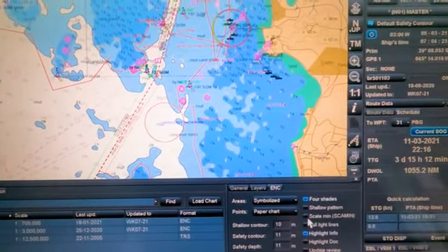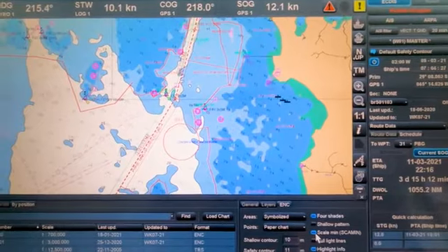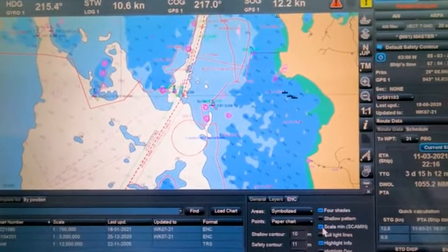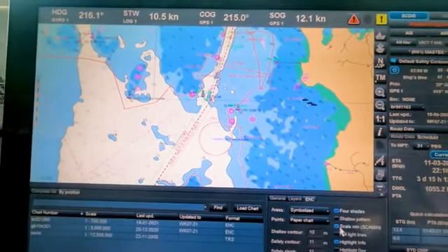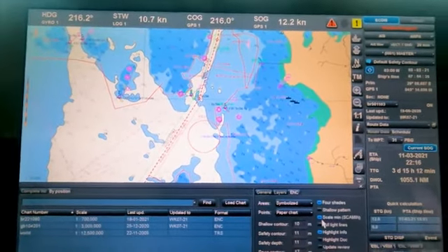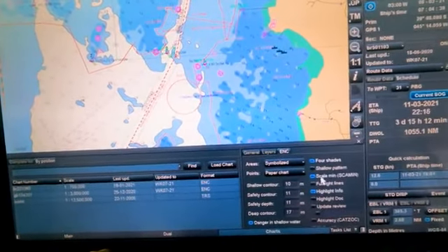And this is scale minimum. The minimum information which is there on the chart, it is used during monitoring, so you can check and uncheck the scale minimum. It's mainly used during coastal passages. In open sea you won't be getting much use of the scale minimum.